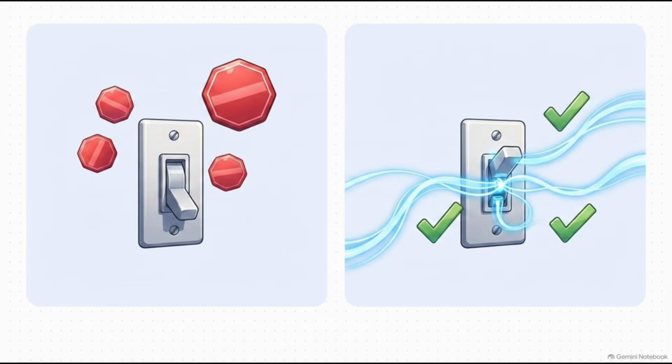Let's picture a scenario, okay? It's Friday at 4 p.m. and you walk up to a completely dead rooftop unit. You throw your meter leads on the switch, you read 24 volts across it, which tells you the switch is open. The rookie immediately unplugs it, clips the wires, and just assumes the switch is bad.